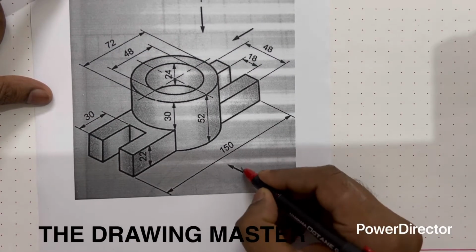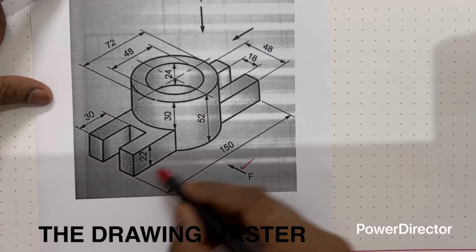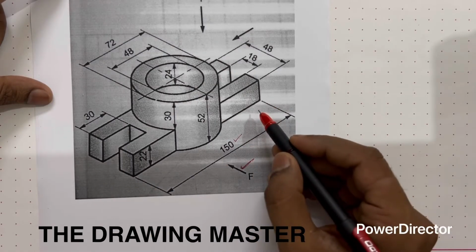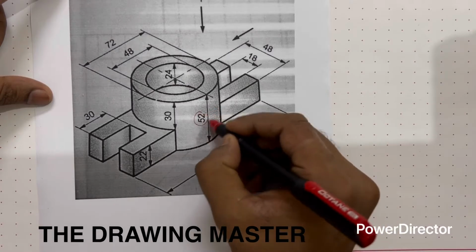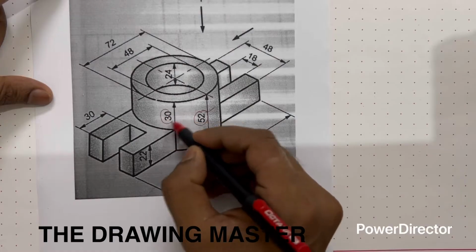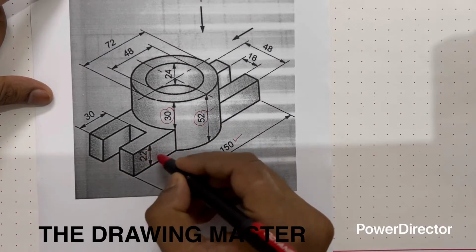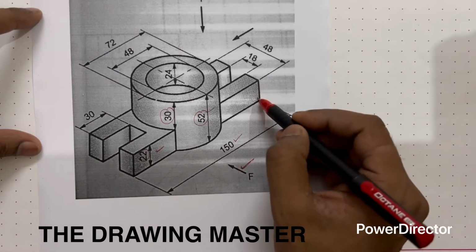So this one is the front view. Direction of view is already given. So total length is 150. From here to here total length is 150. The height of the cylinder is 52. Height of the remaining part is 30, so this one is 22 here. The thickness of this base is 22.